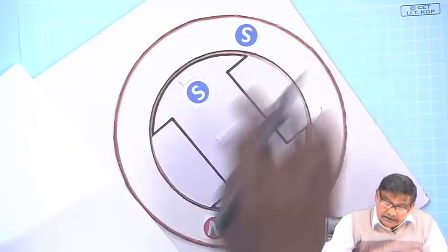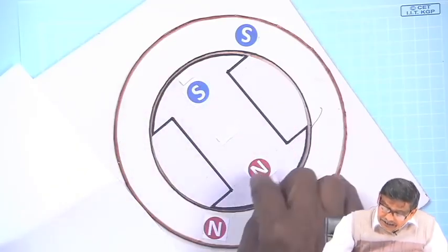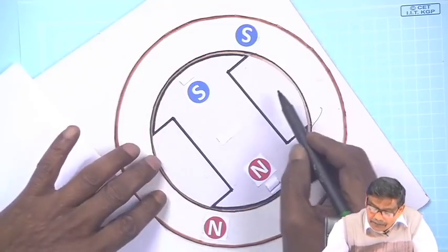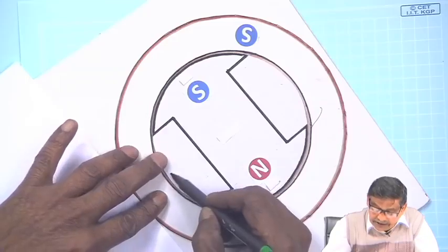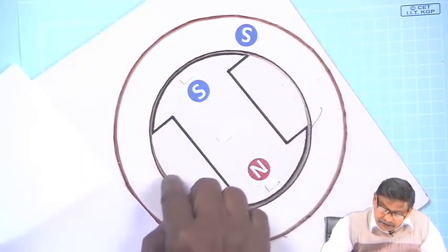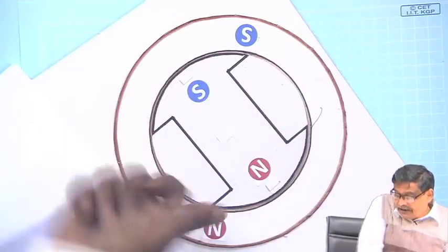So, a stator, a rotor and this air gap. How could this rotor field be created in this direction? The rotor may have some coils here, some coils here in these slots, and if you put cross current here, dot current here, cross current here, dot current here, it will create a north pole.